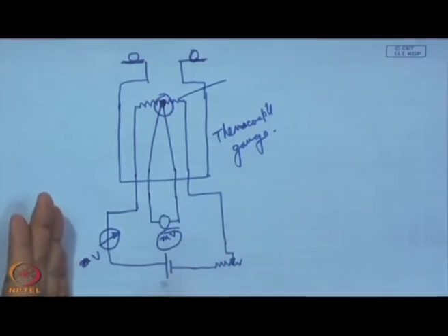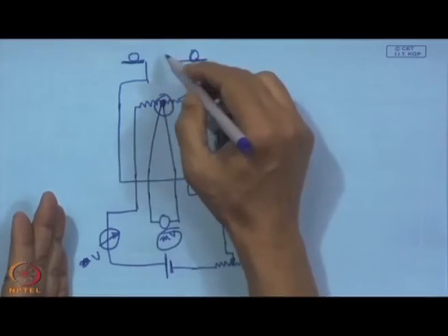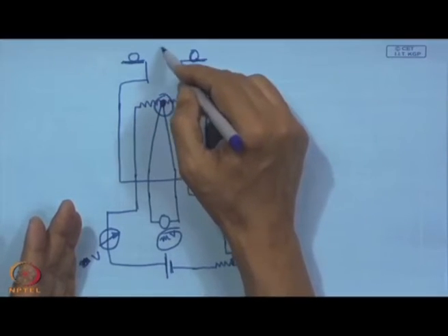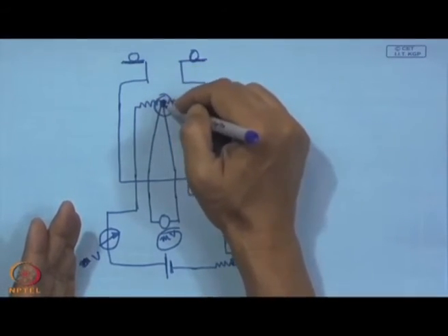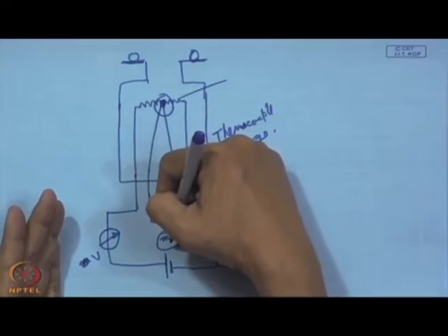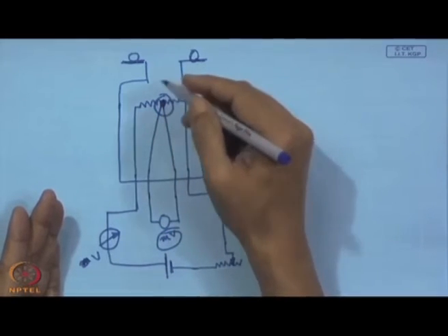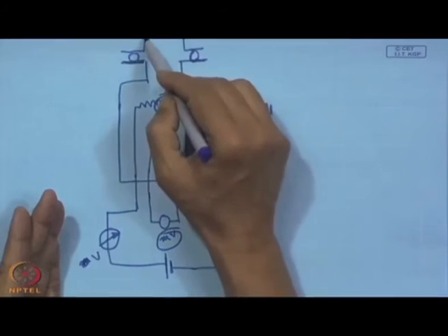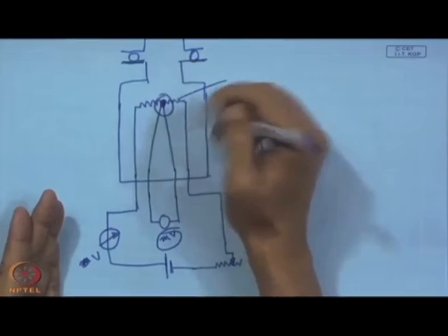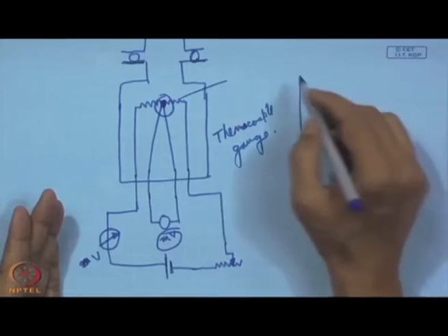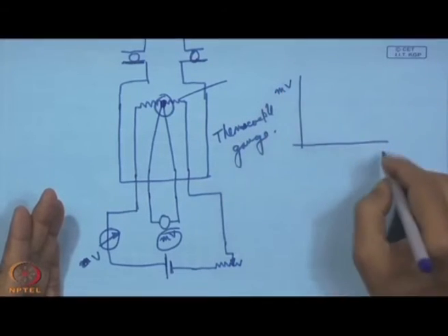So, now with constant heating here, and because of the evacuation, the change in pressure naturally makes the heating effect more, because it will be hotter. If we have more air, then the temperature will fall. So, depending upon the temperature, the EMF will be recorded, and this will be a true reflection of the pressure on this side, which is actually the vacuum chamber. So, this way also we can have such a calibration, and this way we can see this millivolt and this pressure.